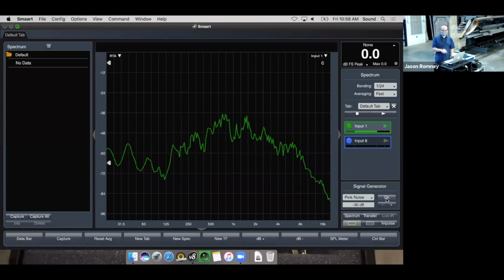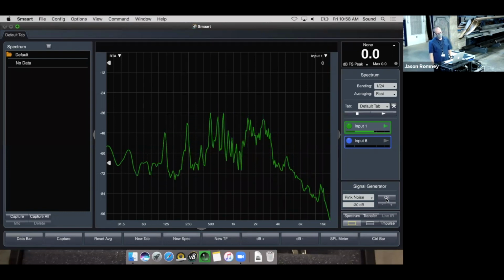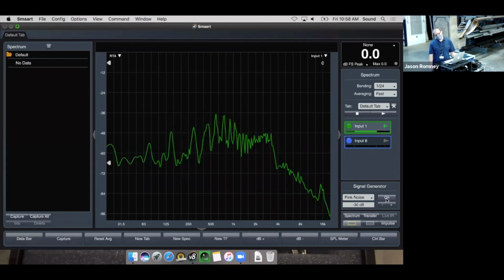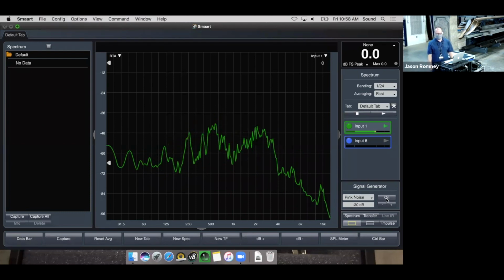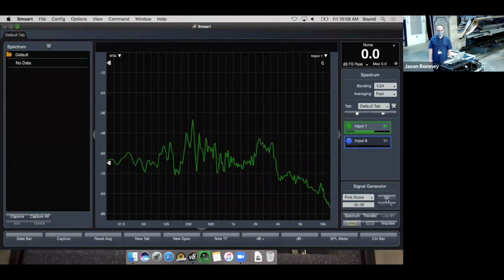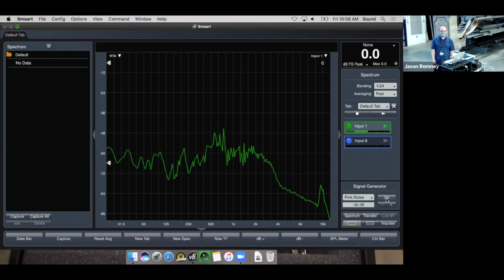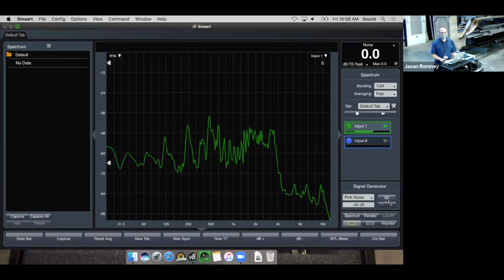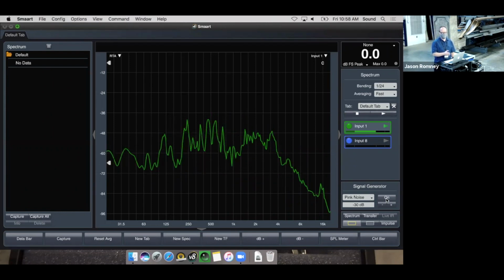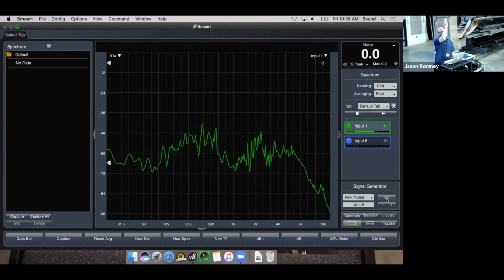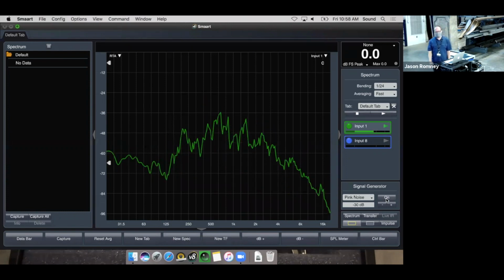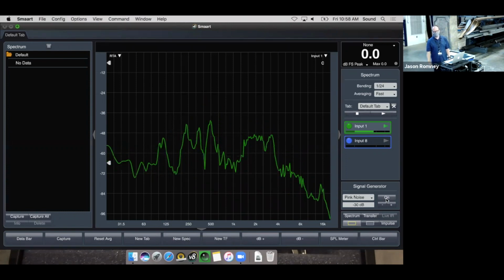But if that's the way you want to do it, this is a good way to find out really quick which frequency you want to take out, along with the 3 million other frequencies you're going to take out when you're notching this out. The spectrum view will show you right away, this frequency jumps out because it feeds back. That's about the only thing useful I've ever seen anybody do with spectrum view.